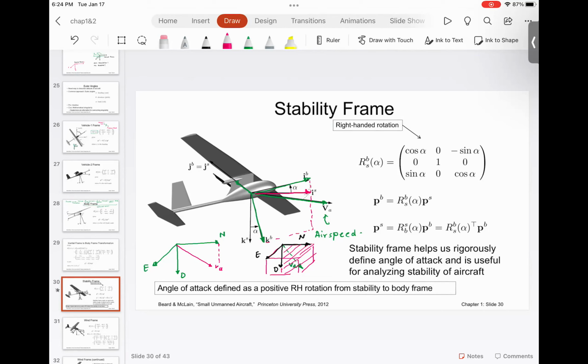But the design of the blades, the angle of the blades, the curvature of the blades, dictate whether that electrical energy or chemical energy or mechanical energy is used to increase the flow energy or the pressure energy. So prop and fan, that is the fundamental. You can't just take a fan blade, attach it to the aircraft and expect that the aircraft will fly.